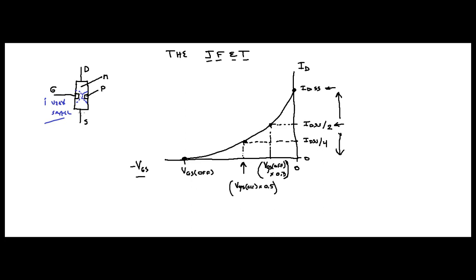They're voltage controlled, and the impedance on the gate is extremely high, which means the current is very low. So you're not going to load down your circuit. Remember, when I say load down your circuit, what I'm saying is you're not going to sink a lot of current out of your circuit.